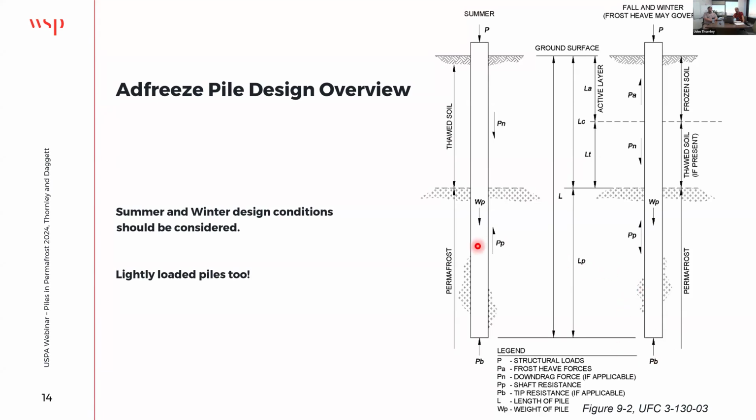What this attempts to illustrate is that one of the things you'll need to consider as you do a pile design is where your loads are coming from, and to understand that they change throughout the year, and that you need to accommodate that in your design. One of the things that's kind of interesting is lightly loaded piles are especially susceptible to the fall and winter frost heave condition, where you end up with an embedment that is intended to resist the force from frost heave.